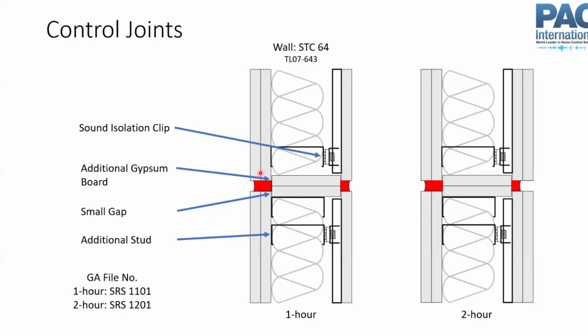So we have a gap here that we've opened up between our layers of drywall that we need to seal. We need to seal it for sound. If it's a fire-rated wall, we also need to seal it for fire. So we put some fire-rated and acoustical sealant. And acoustical sealant is non-hardening, so it maintains its resiliency, so it doesn't create a sort of a rigid bridge between things that could transmit sound. But also it means as this gap moves, it will maintain its resiliency, so it'll stretch and squish with small changes in this gap, so that it always maintains that tight seal. It doesn't open up gaps over time as it dries and shrinks or something like that.